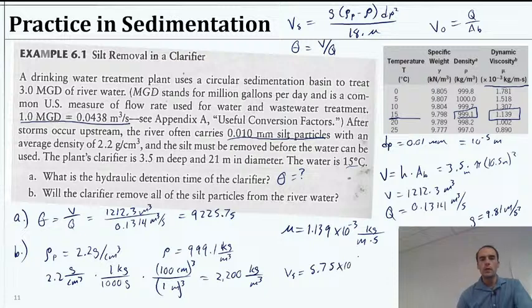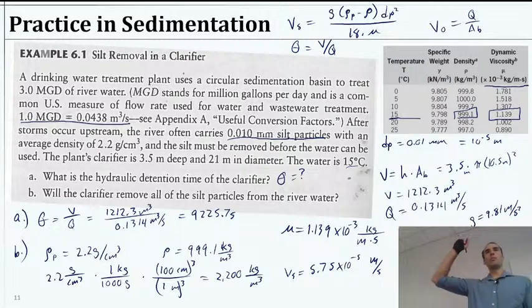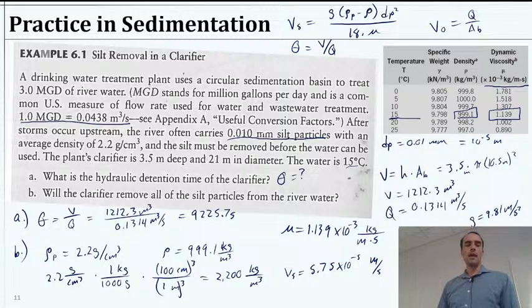Now this number should be a small one because we're talking about meters per second and a very small particle. It's not going to be going multiple meters in 1 second. Right? That'd be extraordinarily fast, like probably faster than a bowling ball would go. So we're not going to be that fast. So it makes sense that this is a 10 to the minus something number, usually 5, 6 range, okay, for particles that we might settle. Maybe sand goes 10 to the minus 4.